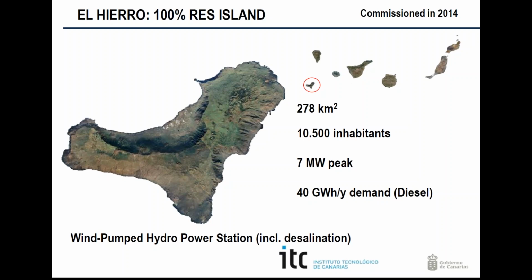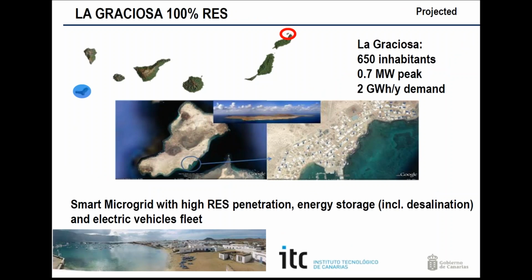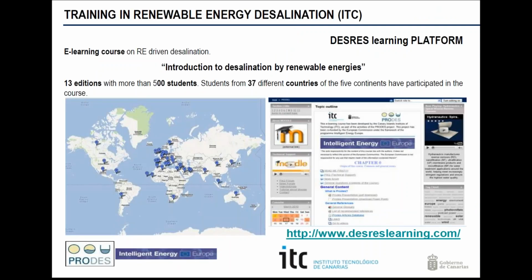Most of the countries with water scarcity exhibit significant solar energy resources. Solar energy can be used directly in the case of the solar still, or indirectly by using a solar collector connected to the desalination plant. The coupling of solar energy with desalination technologies is seen as having the potential to offer a sustainable route for increasing the supplies of desalinated water. Solar photovoltaic combined with reverse osmosis has been a highly efficient reality for 10 years. Currently, thermal membrane distillation and concentrating solar power combined with multi-effect distillation plants are attracting all the interest. The integration of different solar power generation and desalination makes the solar power concept fully sustainable.